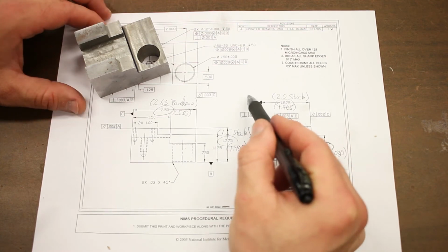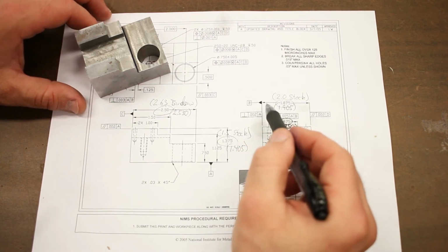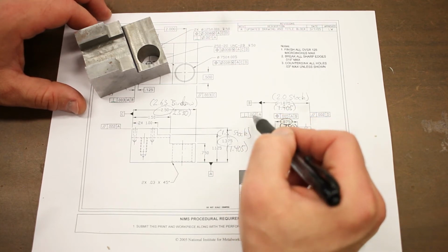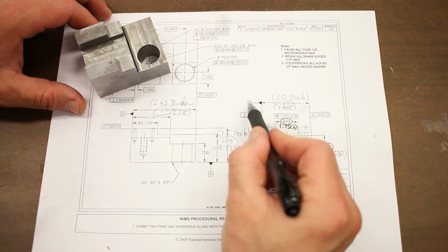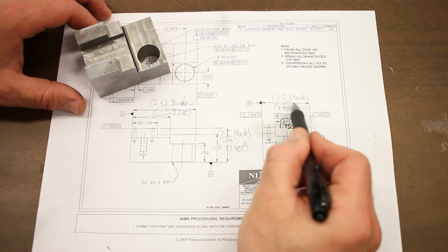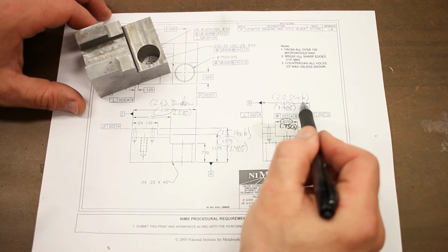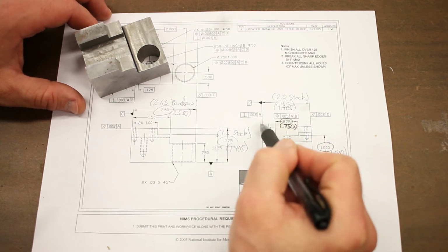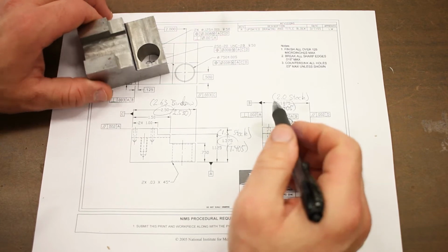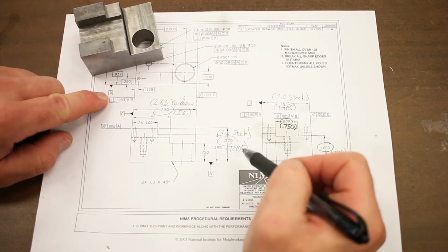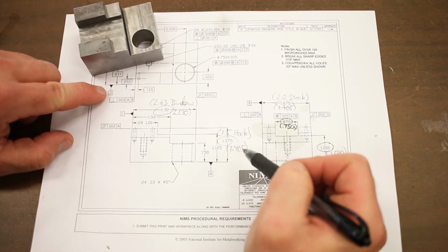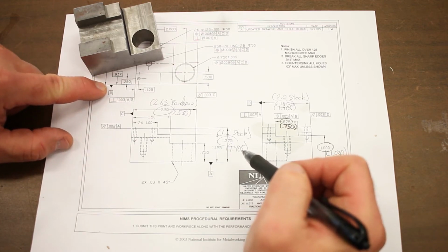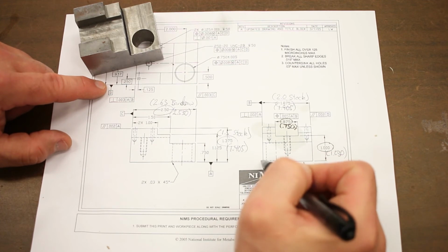In the video where I talk about inspection, we discussed this special circumstance for datum features where the datum identification symbol is in line with the dimension line, meaning that it's actually not this surface, which is datum B. Actually, this surface is datum D. You can see that there the datum identification symbol is not aligned with any of these dimension lines. It's actually just on the extension line. And so this surface right here is datum D.